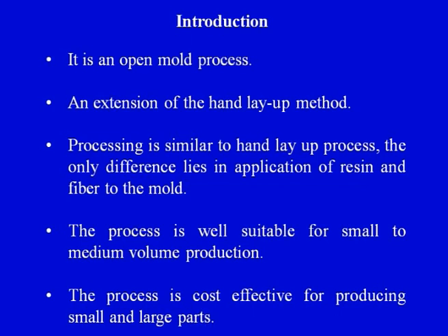Processing is similar to hand layup process, the only difference lies in the application of resin and fiber to the mold. In case of hand layup process, we are putting alternate layers of resin and fiber on the mold. In this particular case of spray layup, we would be using a different method of putting these fibers and resin onto the mold surface. The process is well suited for small to medium volume production, and the process is cost effective for producing small and large parts.